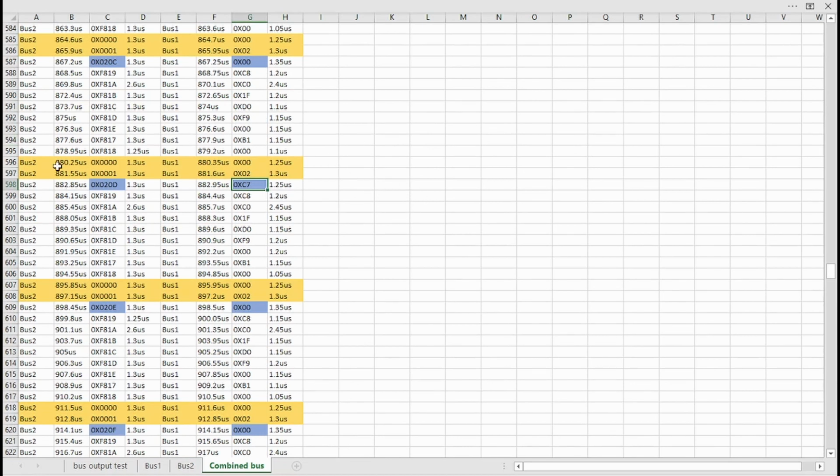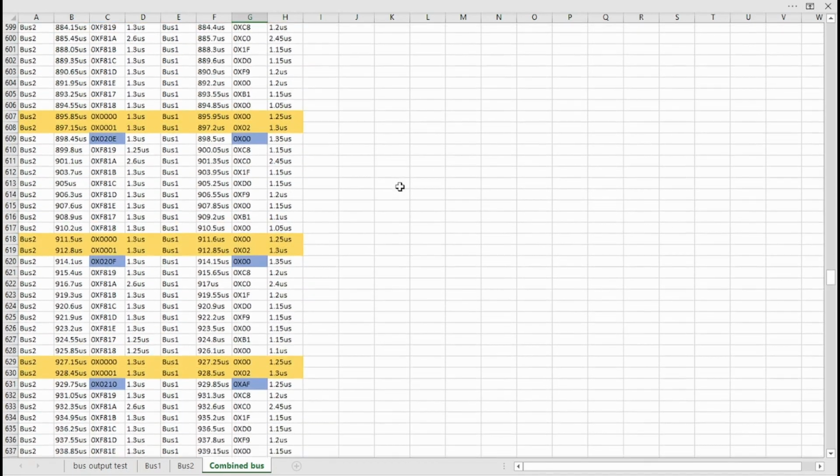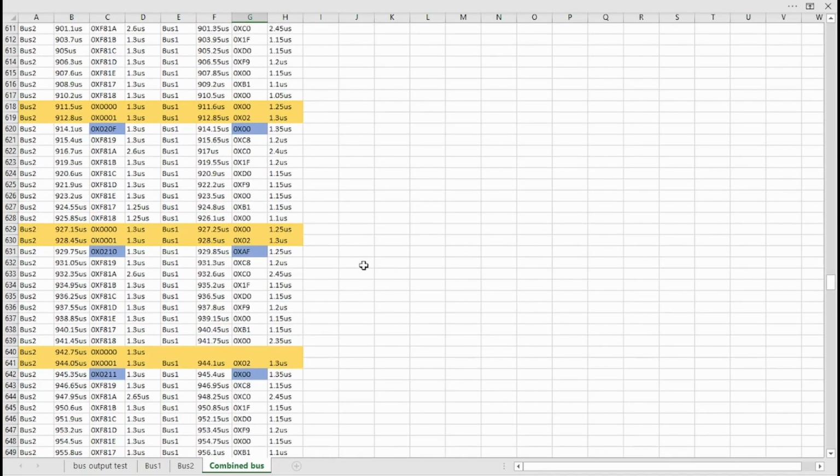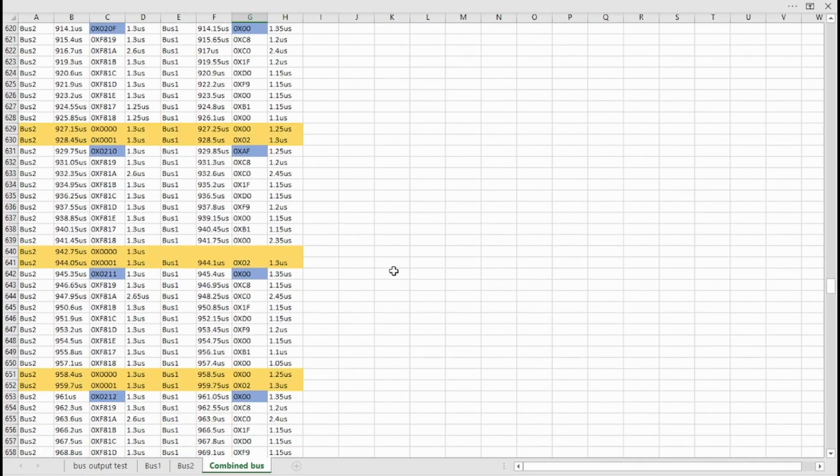And the good thing is this is all happening at 1 megahertz, and we've managed to show that with a logic analyzer. We can now chuck this back into our main circuit and be quite confident that it's going to carry on working at that speed of 1 megahertz and be transferring data from the CPU to the ROM and RAM.